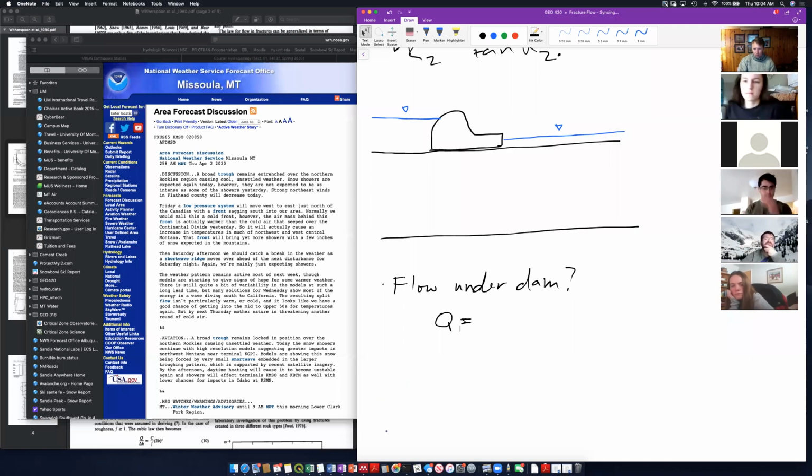Yesterday, we started off with the equation Q is equal to K A dH/dL. Let's think about that transmissivity equation that came out of the book, and why they use transmissivity and why it doesn't really apply in this problem.